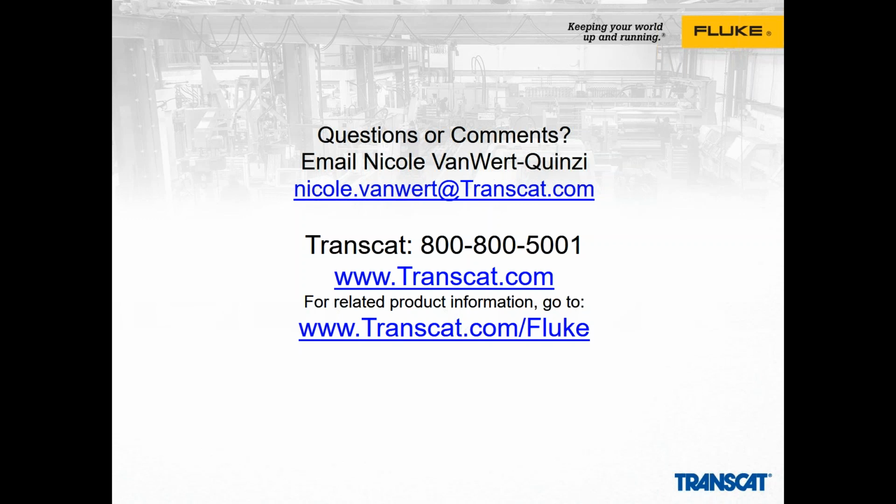They came up with this idea many years ago as a way of classifying whether their equipment should operate correctly. If you're outside of the envelope or the limits, then they will say, well, we can't provide reliable operation. If you're inside, you should be okay. There are also different variations, such as an ANSI standard, which works in the same kind of way. So it's all about the duration of the dip and how much energy is not available.